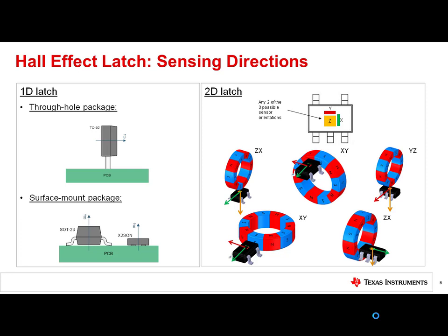With the increased visibility of the magnetic field within a single device, the result is greater design flexibility and improved measurement accuracy. Understanding the field behavior with multipole ring magnets makes 2D latches a practical choice. These magnets are commonly available in either sintered or bonded varieties using various magnetic materials. 2D latches are ideal for applications leveraging rotating ring magnets such as quadrature detection, and are also targeted to support incremental rotary encoding applications.